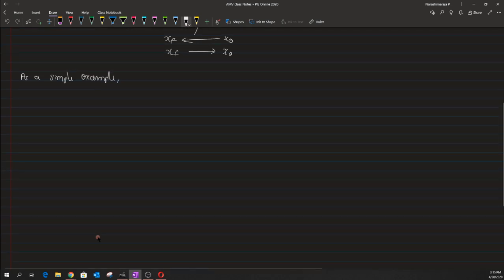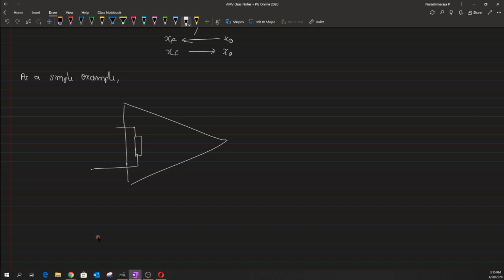Okay, so I'm just going to build a type of amplifier where there can be a considerable amount of input impedance, and the voltage drop across this input impedance of this basic amplifier is considered as Vi, and there will be some sort of voltage controlled voltage source with a gain of A times that of Vi, and there will be some sort of output impedance Z naught, and that is being fed back here.